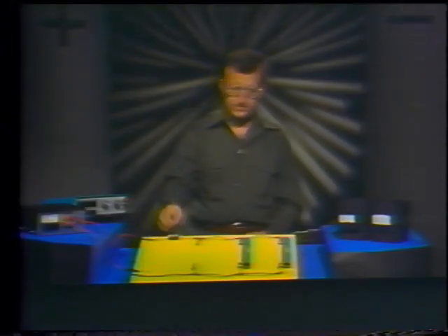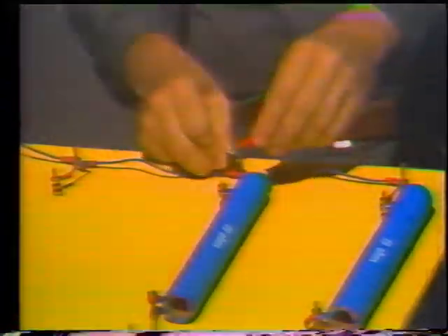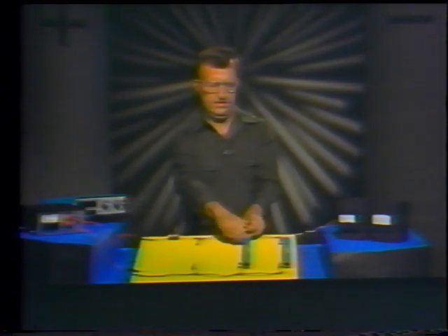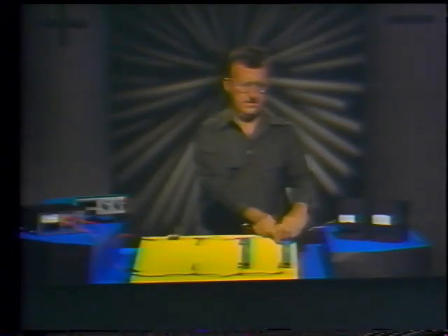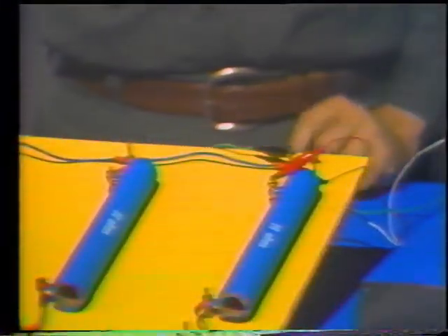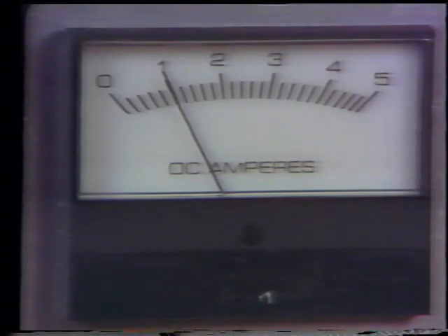Well, let's open the switch and hook an ammeter up to each branch, and we will see what we get. Okay. For the first branch, the meter reads 1/2 amp. So we'll open the switch, reconnect this, and take a reading on the second branch. And the second branch also reads 1/2 amp. The ammeter on our power source reads total current 1 amp. Now, fact 2 checks out on paper and in practice.